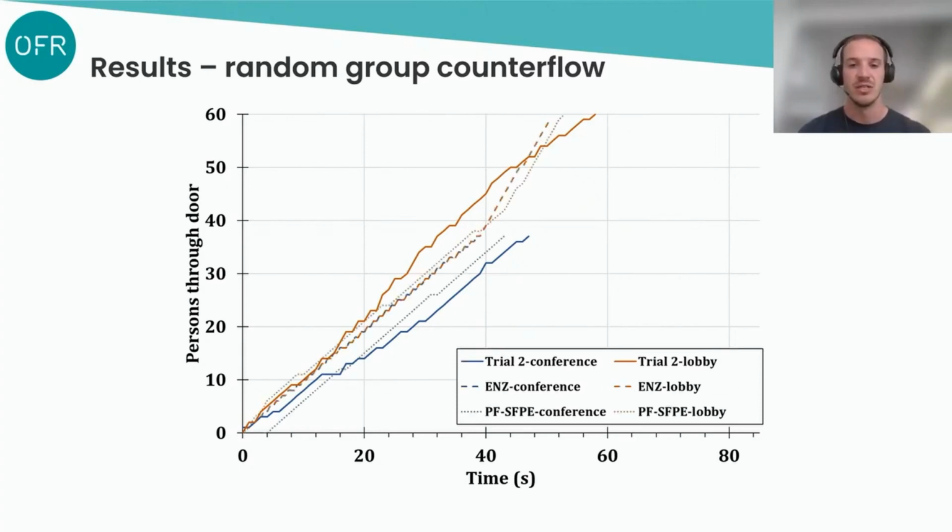So here we can see the results of evacuations in the SFP mode in Pathfinder. We can see the gradient of the model curves increase when the counterflow ceases. You can see the inflection on the two orange dashed lines. This wasn't observed in the trials, but it does make sense from a theoretical perspective, as the effective width the occupants have to pass through the constriction has increased.